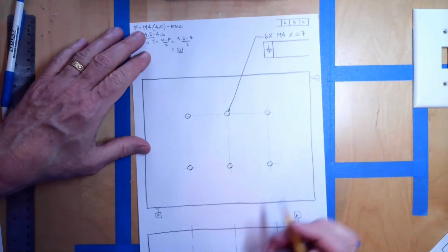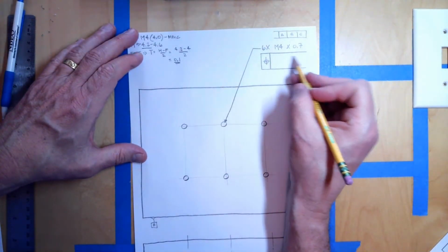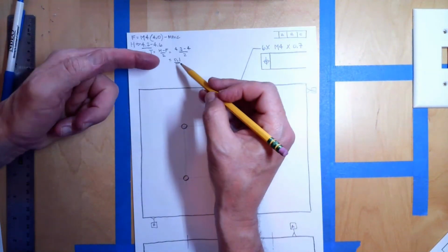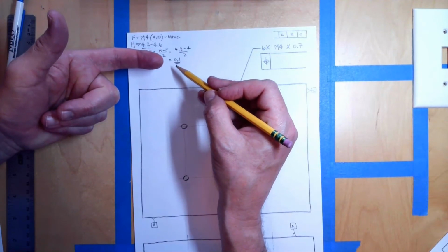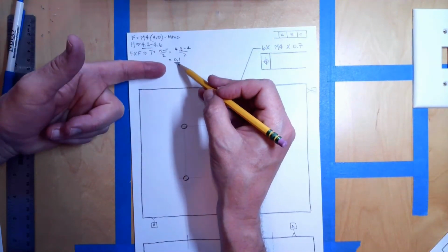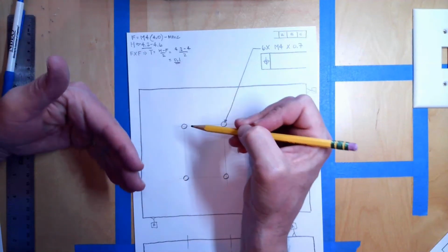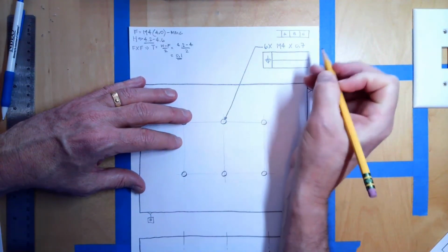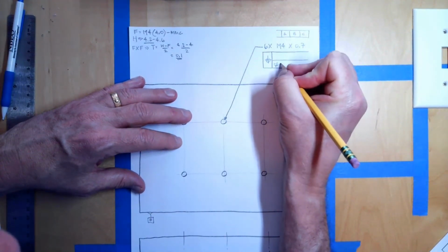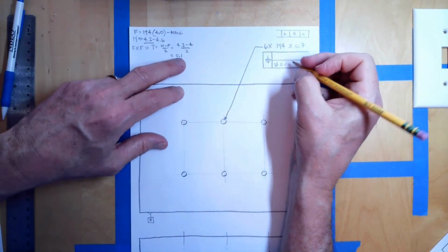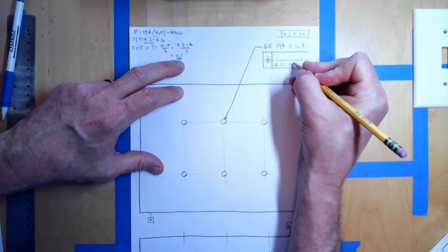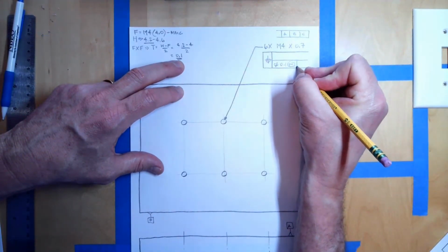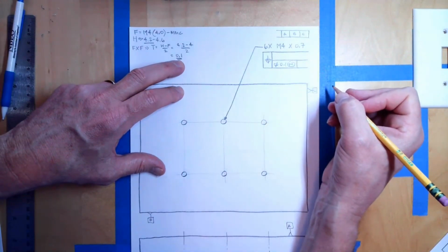Now, which tolerance is that? Is it the pattern locating tolerance zone or the feature locating tolerance zone? Well, this is the most restrictive tolerance, and the tightest tolerance must go on the flats. So this is 0.1. We're going to use MMC because we have a clearance condition, not in the tap necessarily, but in the other one. And let's leave off the tolerances right there.